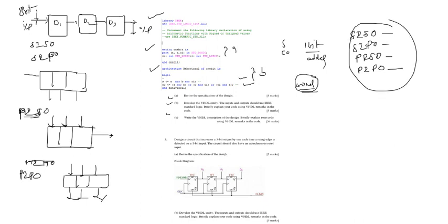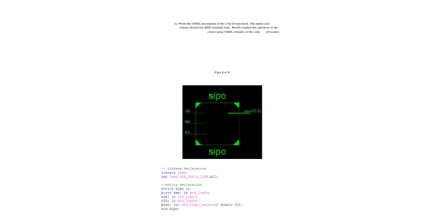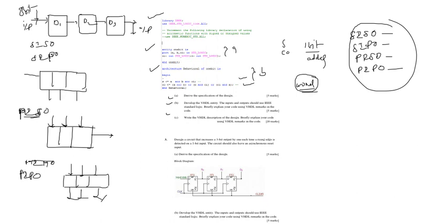So based on these configurations, coming to here, this particular question is given in the form of SIPO, single input parallel output. How single input parallel output? You can see here. Design a circuit that takes a 3-bit output. 3-bit output means under the specification it takes 3 parallel bit output. Each time a rising edge is detected, a 1-bit input. This is 1-bit input, that is basically a single serial in, and this is parallel out. So serial in parallel out specification is given in the question.